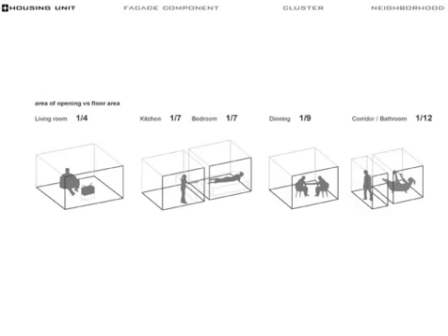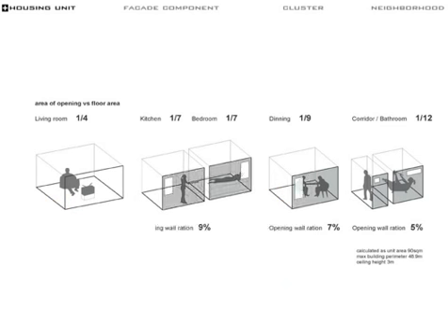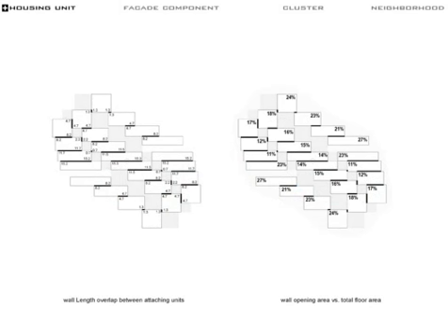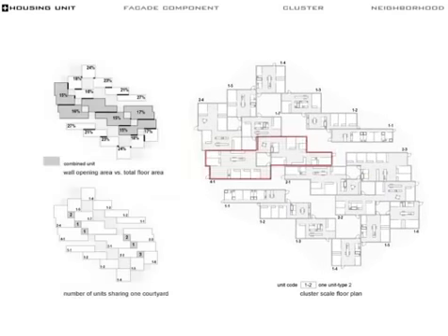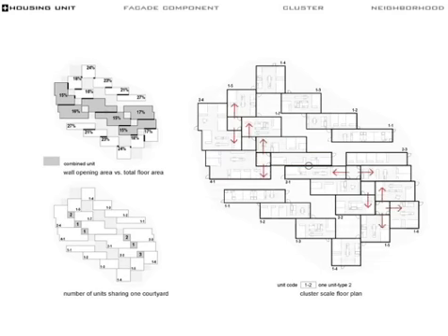It is regulated in the housing environment. Each functional area has a given percentage of wall openings. The living room standard is chosen for the maximal requirement, calculated as an opening ratio of 15% to the total floor area for this model. When assembled, individual units can merge together, optimizing the building envelope to achieve the optimal 15% opening surface ratio. This operation allows a maximum of 4 units joining together, sharing one internal courtyard. These variables in unit layout facilitate different social interaction through courtyard distribution with surrounding units.